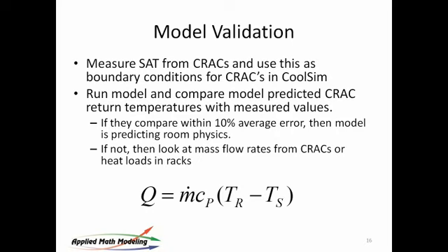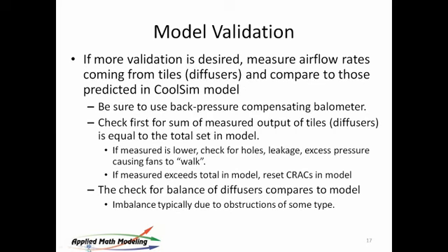So, and what's going on under the floor. They can also be walking a fan curve too. That's exactly right. So if the delta P is too high, if there's too much resistance under the floor, if the subfloor is 8 inches or 6 inches, or there's 30–40% or more of the cross-sectional area blocked, then it's likely that the fan will not be producing what the spec is, because it's got too much pressure drop across it. So that's something to look for.